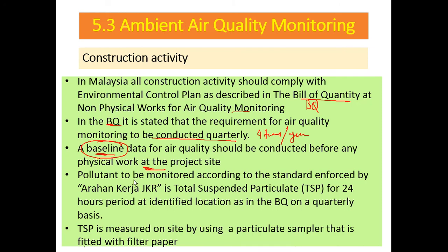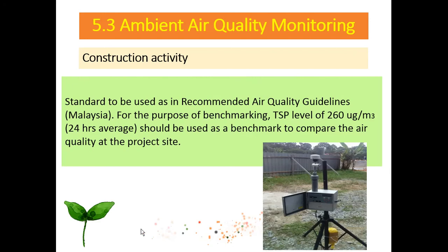Okay, the pollutant to be considered, the standard for Arahan Kerja JKR, is the TSP, total suspended particulate for a 24-hour period at identified locations in the BQ on a quarterly basis. TSP is measured on site by using a particle sampler fitted with filter paper. So this one is the device or instrument used to measure the air quality. Here we fill it with filter paper, and the filter paper will be measured for the TSP.